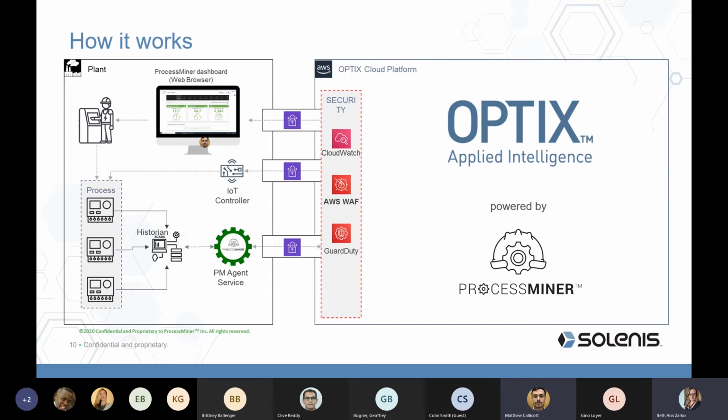And so the next step that we've talked about, the autonomous control piece, is now using an IoT controller, the Solenis OnGuard controller, and using this real-time prediction and a feedback control loop with a chemistry lever to optimize that lever and drive that KPI, that prediction, where we want it to go. The really cool thing about the system is we can decide where that is.